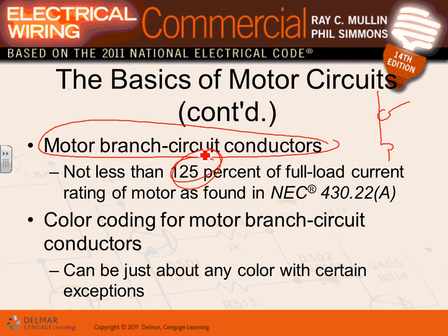I told you, when you guys leave the chat, if anybody says, I have a branch circuit, size this branch circuit for me, and here's the amps for it, 100 amps, and you don't know anything about it, what do you say? You say, oh, 100 times 1.25, that'll get you 125 amps, size the conductors. If you say that, you are right 90 to 95% of the time. Always consider it a continuous load. That's why the 1.25. Get the amps, multiply by 1.25, size your conductors, for appliances and motors and what not.